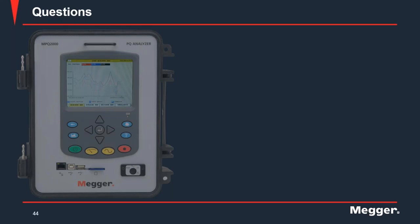Whenever you hook up a power quality analyzer, we want to make sure that we record all the necessary data. Typically with our units, when you select one of the default setups that are in there, you're going to be recording everything, so it's really not an issue. You can really just start recording with them. And when you do that, you're going to get all the harmonics, the interharmonics, all your swells, sags, transients, rapid voltage changes. Everything occurs. You'll get total harmonic distortion and total demand distortion.